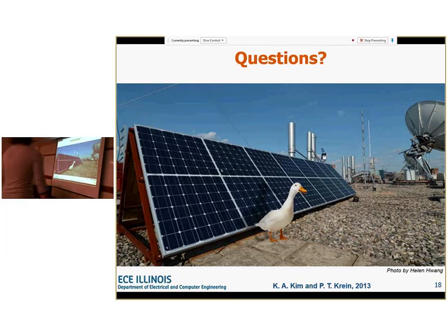So you found that 2x was sort of a safe place. How does that correspond to the duck? As in, if you have 12 of these, say in a string, and they can all produce full maximum power, right? So in the worst case, it can be an 11x power through one of these cells. Have you done any correlation between the shading pattern and how much shading that constitutes?